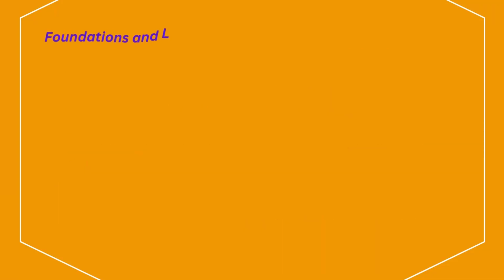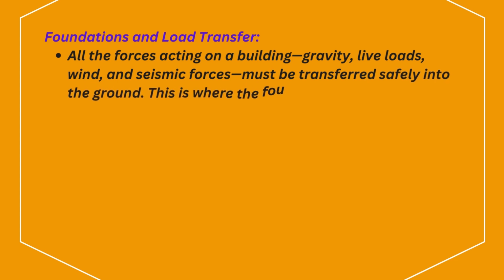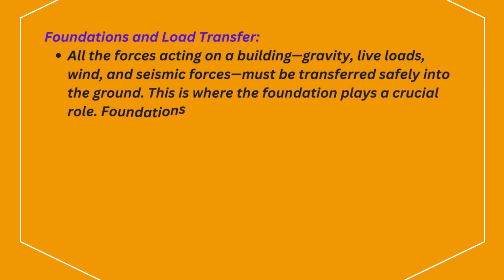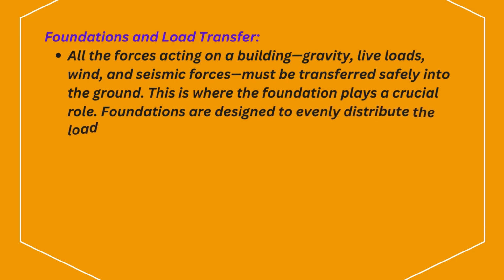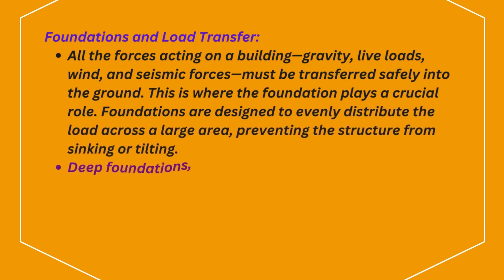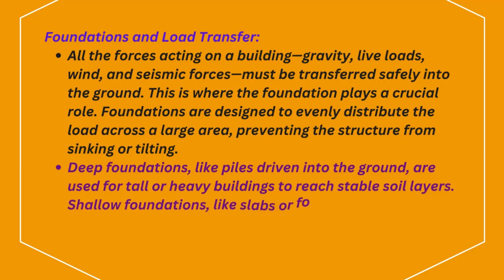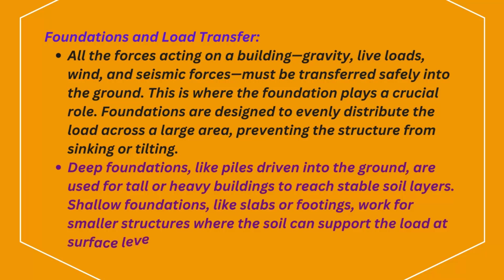5. Foundations and load transfer. All the forces acting on a building, gravity, live loads, wind, and seismic forces, must be transferred safely into the ground. This is where the foundation plays a crucial role. Foundations are designed to evenly distribute the load across a large area, preventing the structure from sinking or tilting. Deep foundations, like piles driven into the ground, are used for tall or heavy buildings to reach stable soil layers. Shallow foundations, like slabs or footings, work for smaller structures where the soil can support the load at surface level.